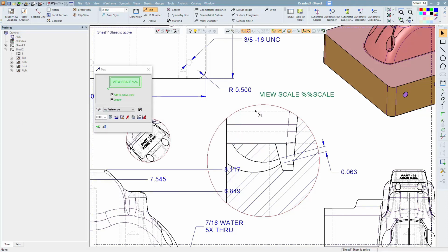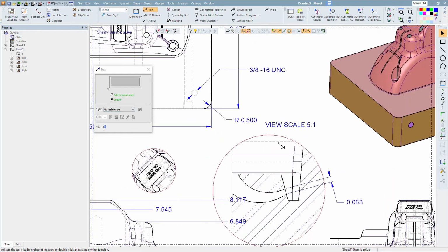Most symbolic text will still show the variable name on the screen until you tell the system where to find the info. And this is done by attaching the text. You use the attach button and then select the view that will supply the information, and then approve. This step of attaching the text is absolutely necessary for any symbolic text that links back to a part attribute. So you have to consider attach a key step in order to get your symbolic text notes to work.